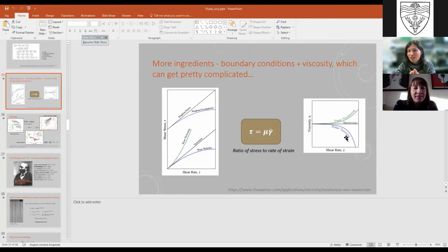So you formulate the ink so that it tends to do that. And then there is another thing. Generally, not with all inks, but you tend to increase the temperature a bit. So you may not be working with room temperature. You may be increasing the temperature of the ink. Could be 40 degrees. It doesn't have to be very, very high. But that means that also the viscosity is a function of the temperature. So increasing the temperature tends to generally decrease the viscosity. So you both work with, again, that sort of behavior of a slow or fast flow, and again the temperature.